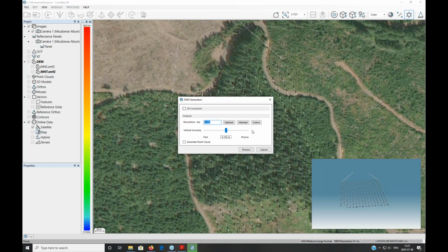output data. And also, optionally, there's a point cloud that can be generated from the input imagery, and this point cloud can be colorized with the multispectral band. So at the end, if you want to export a point cloud, you can have a point cloud that's going to contain color information. It can be RGB, it can be CIR, depending on what point cloud you want, but you can select what band you want to use later on to colorize your point cloud.